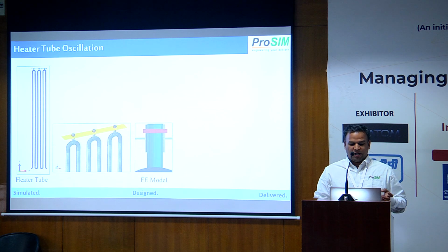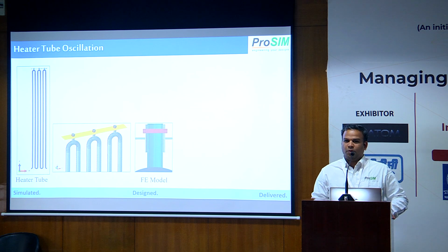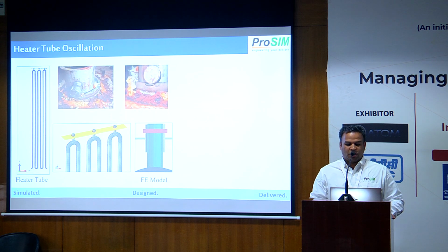So we captured again the material modeling. You can see the pin at the upper part of the tube, where it is connected at the outer tube and the inner tube, and the overall load is taken by the pin only. If you see the physical image, it was corroded because of the contact between the tube pin and the tube. So this calls for boundary nonlinearity.